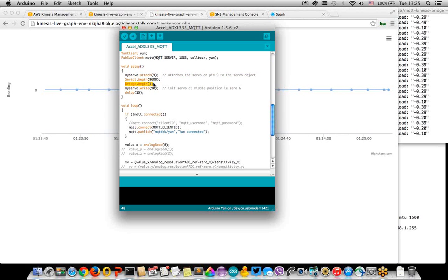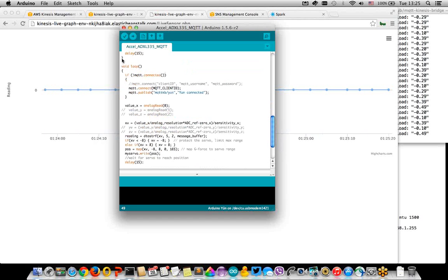We start the bridge, which gives us connectivity. And basically first I zero the servo. So I set the servo to 0, and my analog display will start from 0. And then the loop function in Arduino is looping around endlessly. This is your main program.